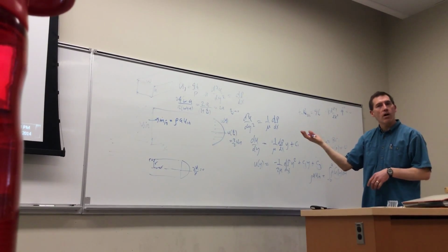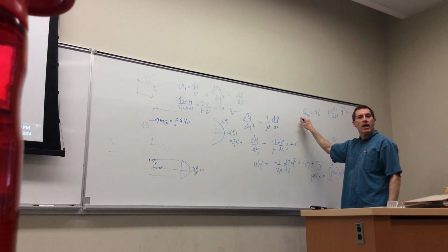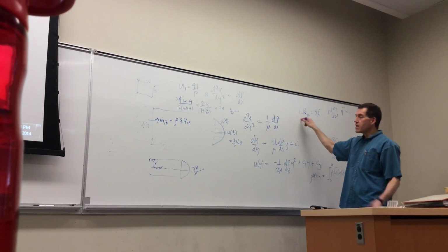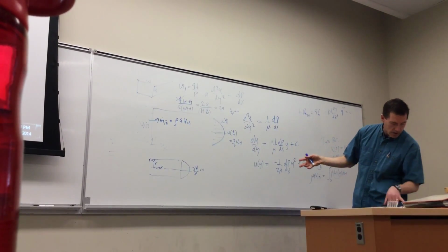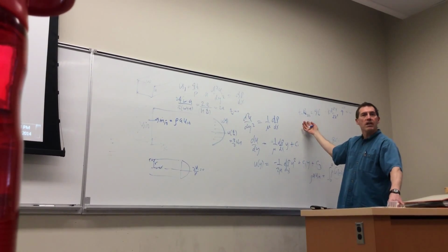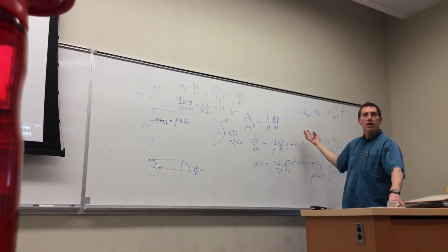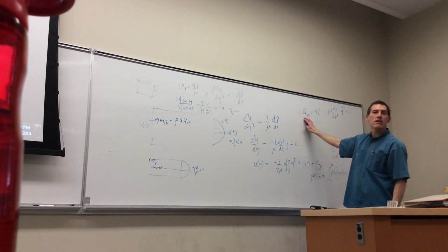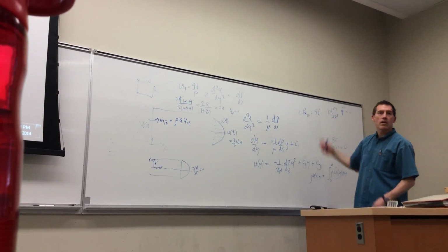So it's either tau wall or dp dx. If it's dp dx, you have an expression for dp dx, right? Yeah. Then you take the expression for dp dx, you divide by half rho u n squared, and you can collect the rest of the stuff into a Reynolds number, and you'll see friction times Reynolds equals 96.